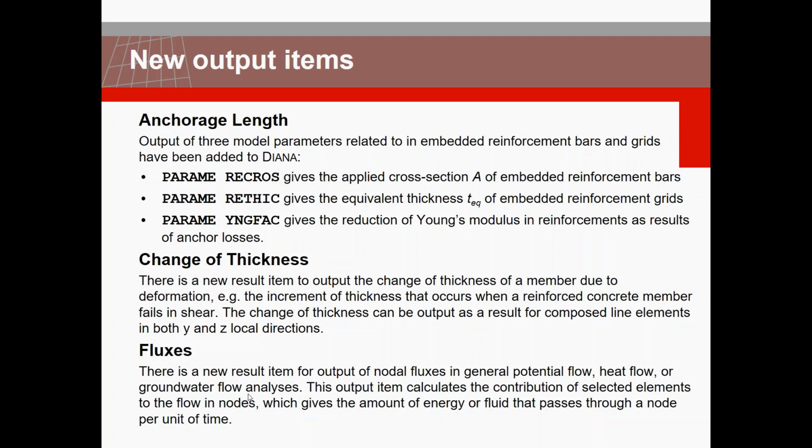The flux output, now you can easily select a group of element sets, the associated nodes, you can highlight them, and it doesn't matter if you're dealing with the heat flow or groundwater flow. Any type of energy or fluid output can be measured through these nodes associated to those elements per unit of time.